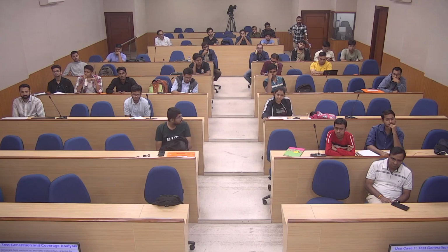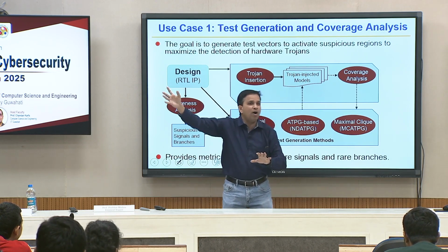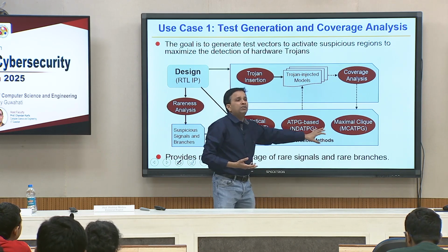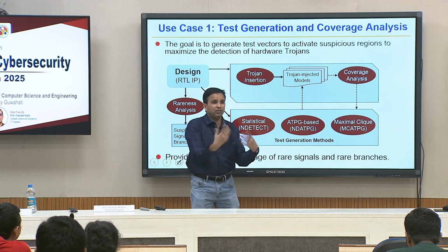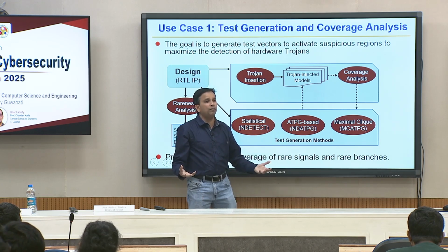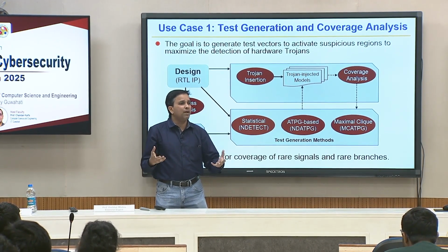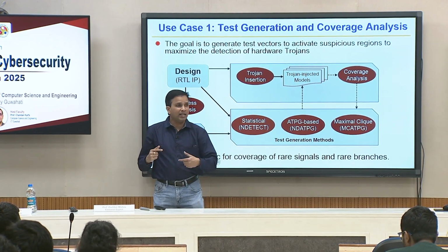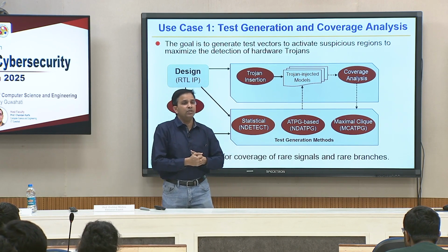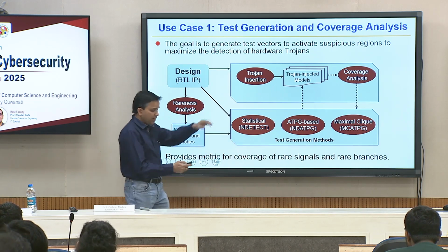Absolutely correct. You are doing all this to set up your environment, because your design is going to go to all these places in the world. When it comes back, what confidence would you have that your framework would be able to detect the Trojan? Even the Trojan you inserted, if it is not able to capture those, then you know you will not be able to capture others. But if you can capture all of them, you have good confidence we did build a good framework. You are just validating your framework. Recall the example I took, if you hired a bodyguard, you hire an attacker, make an attack on yourself to see how the bodyguard defends, so that in a real world scenario you know how that bodyguard would protect you. So this is the same analogy, and this is one way companies use it.